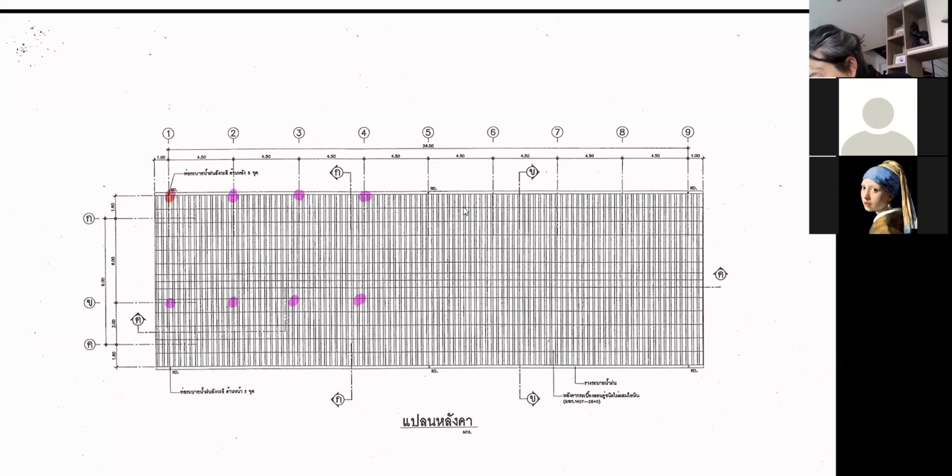We'll discuss this matter in more detail, but now I just want you to gather information about the load first. Okay, no need to design anything. So this is going to be the rough sketch of your roof plan. Now these are your columns, right? And perhaps you can just use one type of truss. Because this one will support the load slightly more than this one, but it's just one and two on the outer rim. So you may use the same details for quick construction.